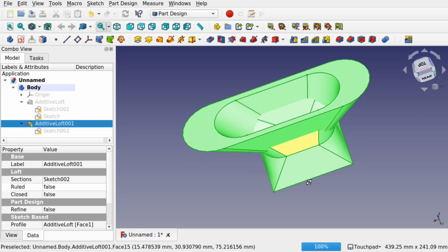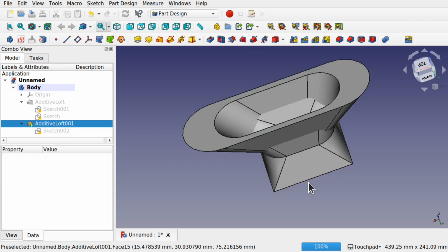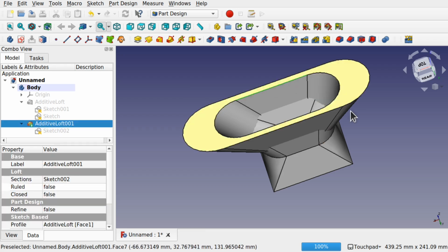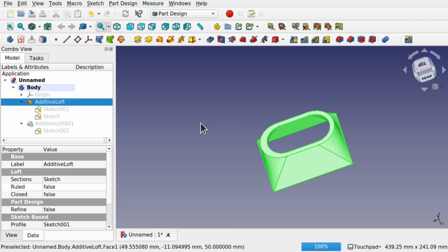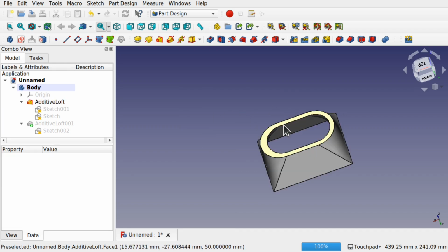So just be wary of this when you're creating the models. I've only come across this problem recently because when I very first started CAD, it was taught in a certain way. So I've been working all this time not knowing this existed. In other CAD programs and other 3D programs, you have a choice when actually creating these lofts. Sometimes you can actually select the edges, so outside, inside, and then when you select the other part of the loft, let's say this part, you can select the outside and then the inside and then create the loft between those. With FreeCAD, it's all to do with the arrangement of how you create that geometry in the first place.